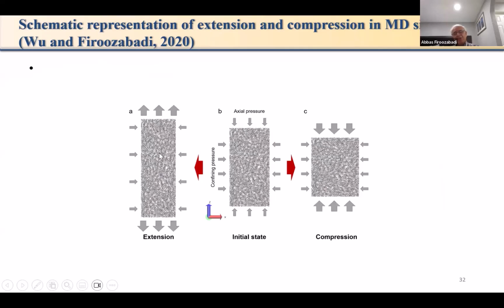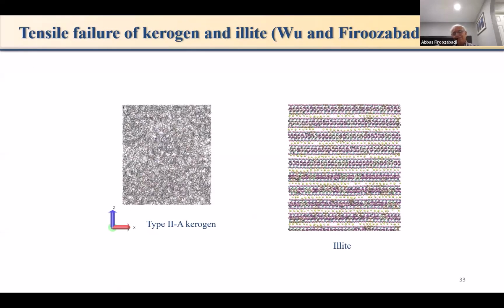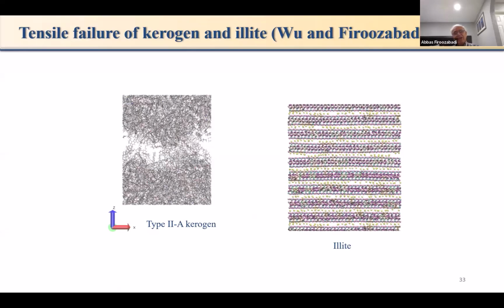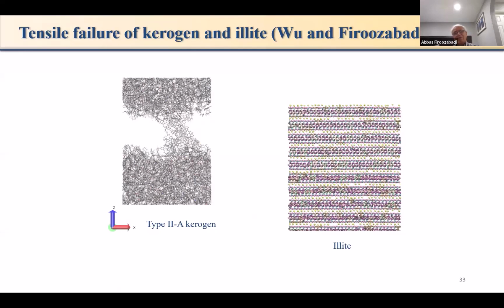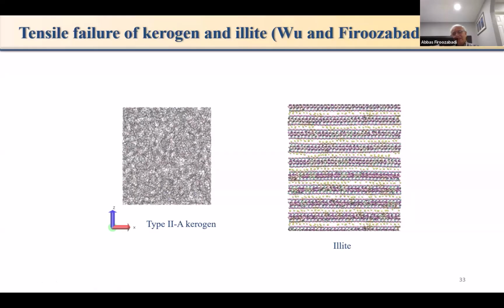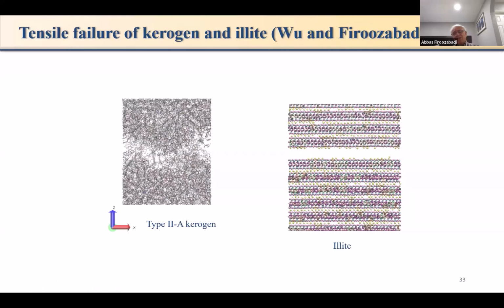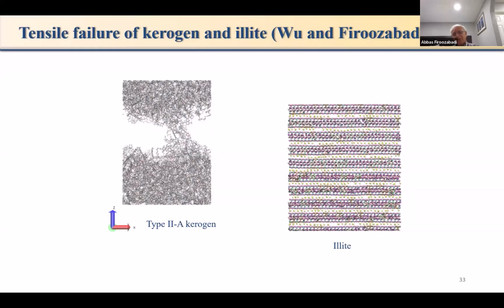So this is the kerogen part of a shale. We have constructed kerogen; we can stretch it, we can compress it. And from this, you may be able to get Young's modulus and some other parameters too. So this is basically the molecular simulation we did. We took 2 different types of media, illite and also kerogen. Kerogen is just a very flexible molecule, and what we do is displace atoms about 0.5 angstrom in every step and wait for a while to get near equilibrium.